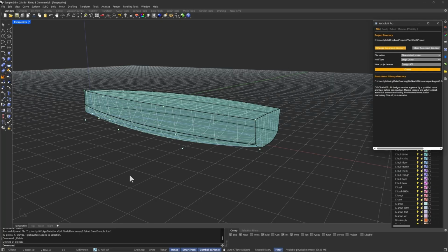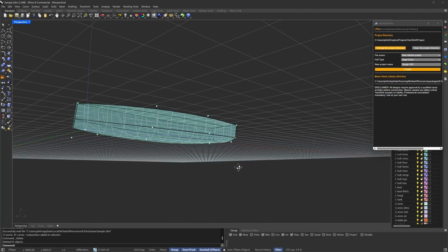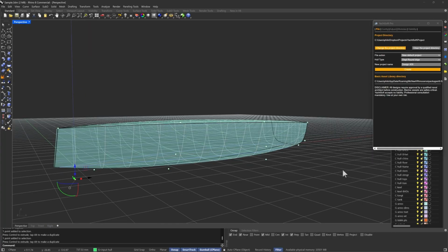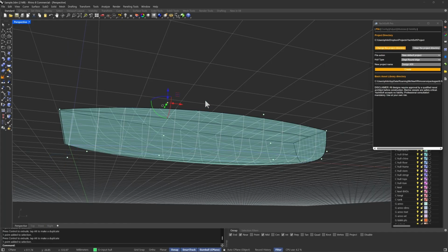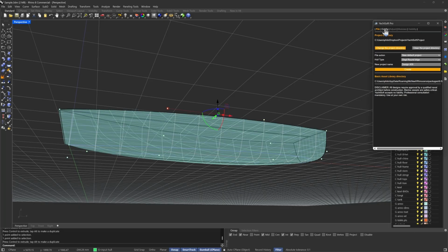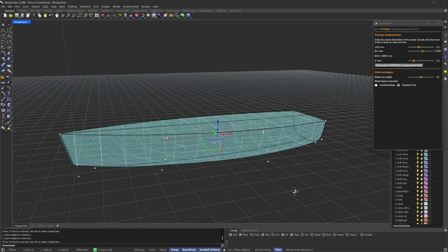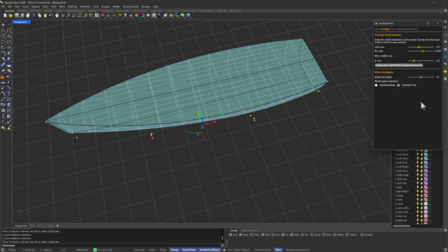It generates a hull for you automatically, and you have the ability to control any and all of these points here. So moving these will change the shape. And probably not a reverse shear, so these points could go down. So a more traditional boat. Transom and bow I'll explain a bit later. A chined boat.